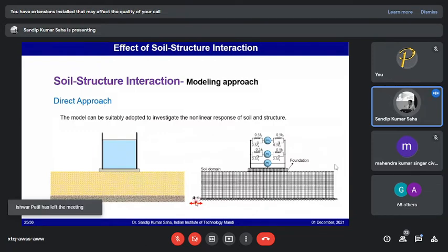With this, you apply absorbing boundary conditions, because if the soil domain has finite dimension, there will be issues of reflection from the boundary. So we need to ensure how large the domain has to be taken. For every structure, the domain of the soil in the numerical model plays a crucial role. Also at the boundary of the domain, we need to apply absorbing boundary conditions, so that there is no reflection of the seismic wave. If some waves are coming, they would not get reflected from here again. They would escape the system without changing the interaction between the foundation and the soil domain.